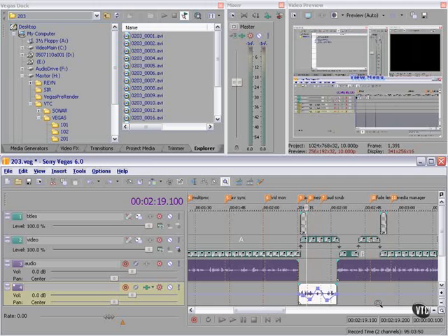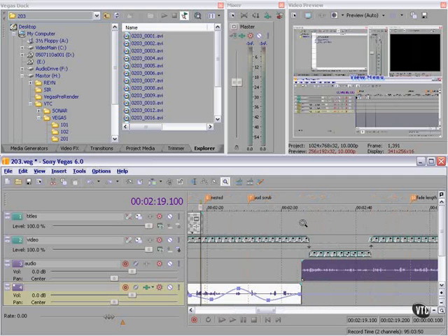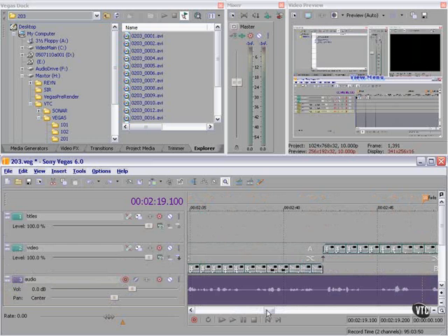The Zoom tool also has 3 modes in the same way that the Selection tool does. If, while holding the left mouse button down, we click the right mouse button, we change to horizontal orientation. If we click again, we change to vertical orientation. If we click a third time, we're back to the normal free zoom.